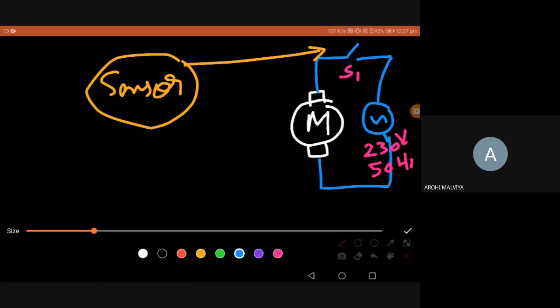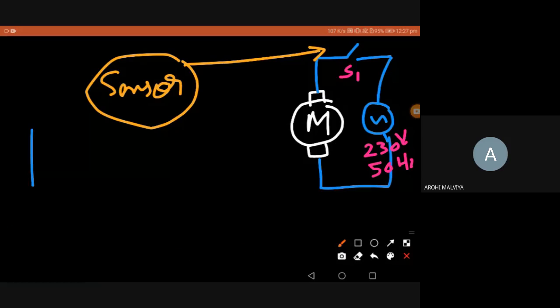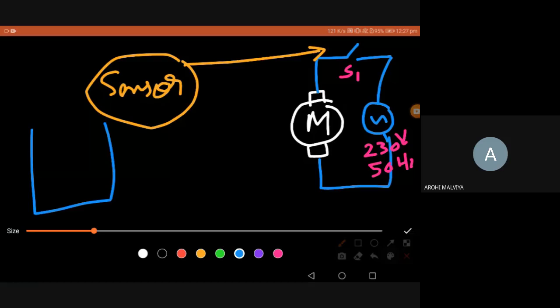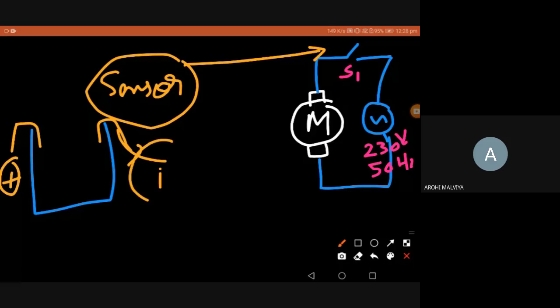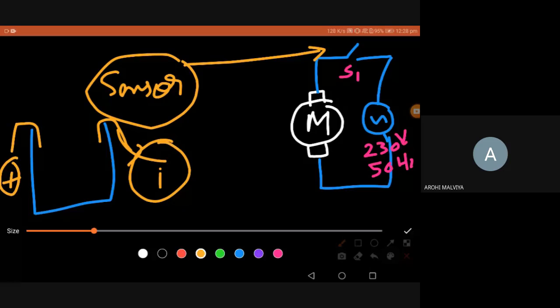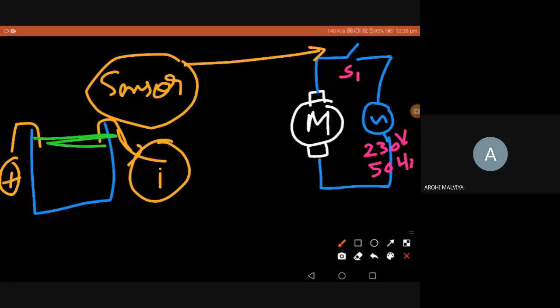We already know what kind of sensing we can use. One very simple idea is what we already discussed. We can have a tank with two conductors, at the top position and the bottom position, and we can have a positive supply. When they connect here, I can have a current or voltage here, I or V, in the output. So this acts as a sensing mechanism. If and only if the water level is full, I can give an indication here, 1 or 0.